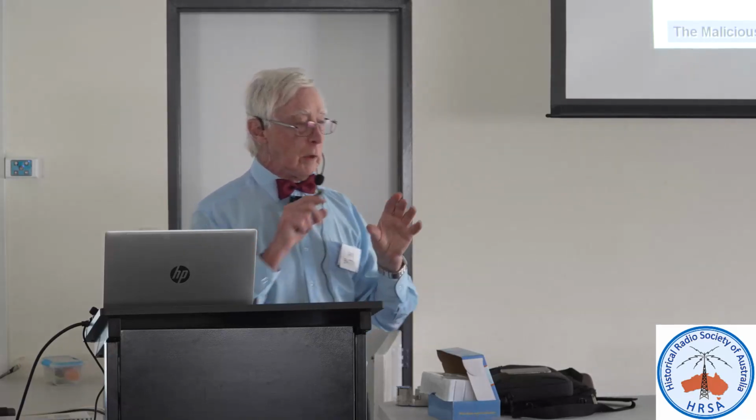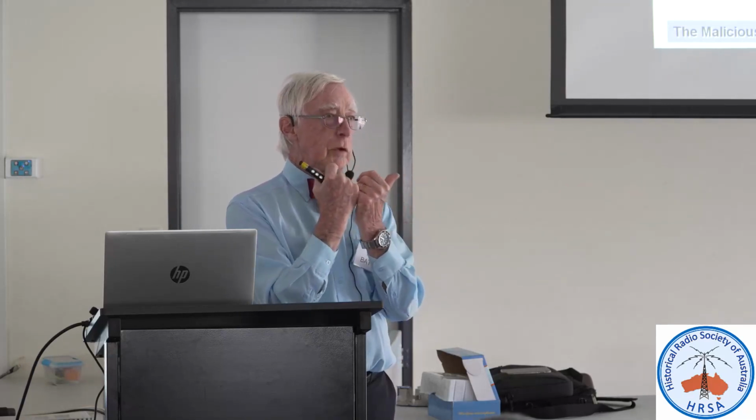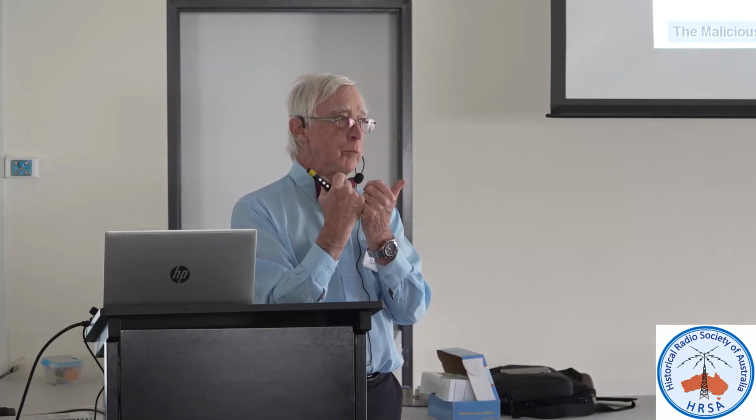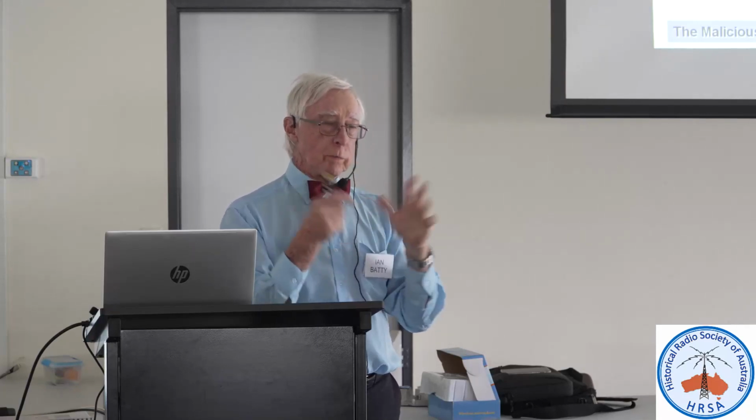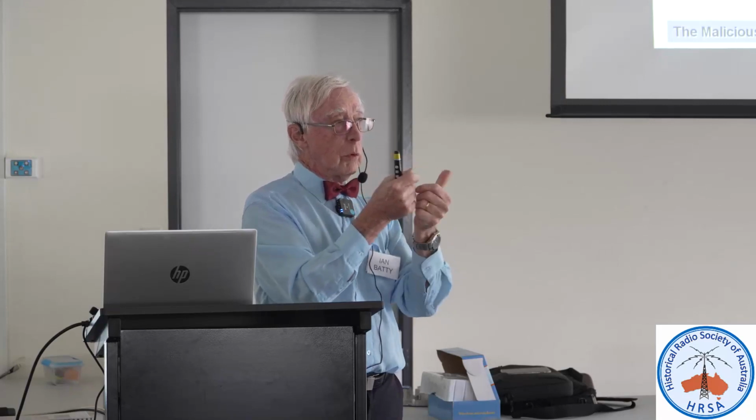Some sets actually, in the cord hole, have a rolled edge, which is considered safe. It's still not my preference, but if you have a set with that, then I'd probably leave it, but make sure the cord clamp is secure so that the cord can't pull or rotate.